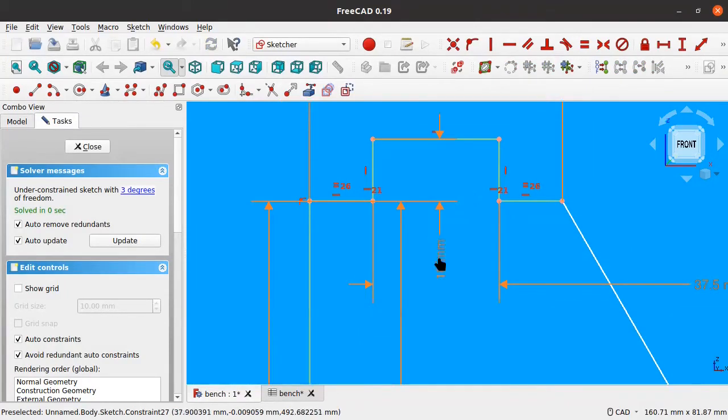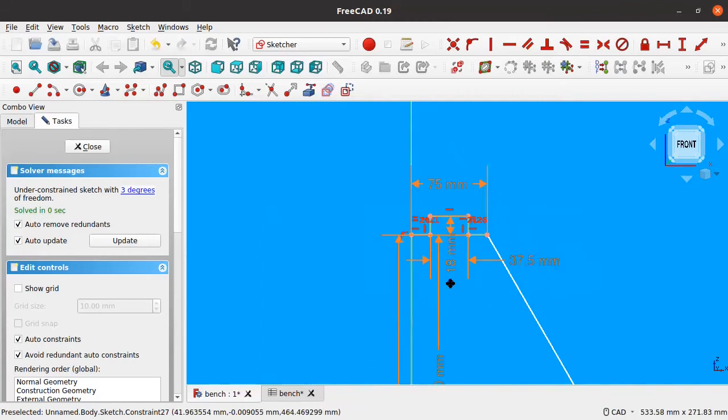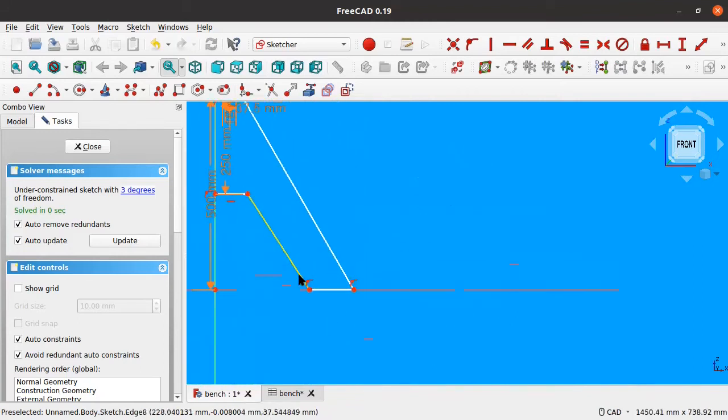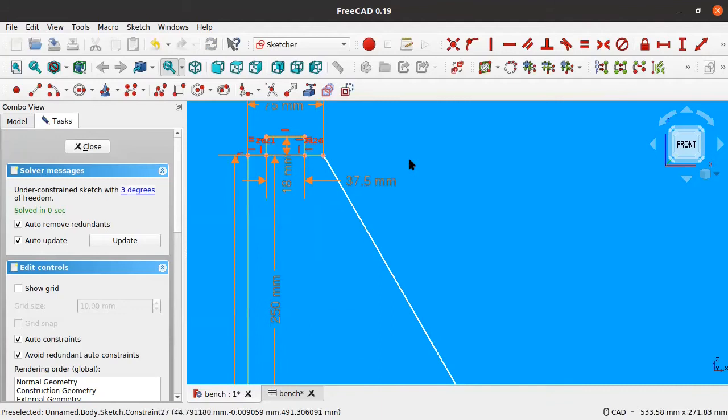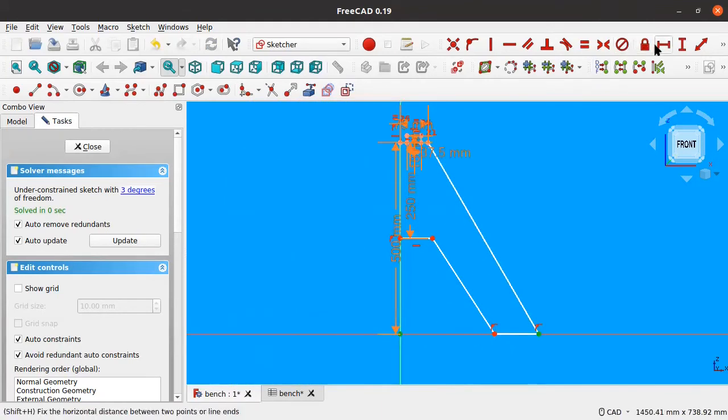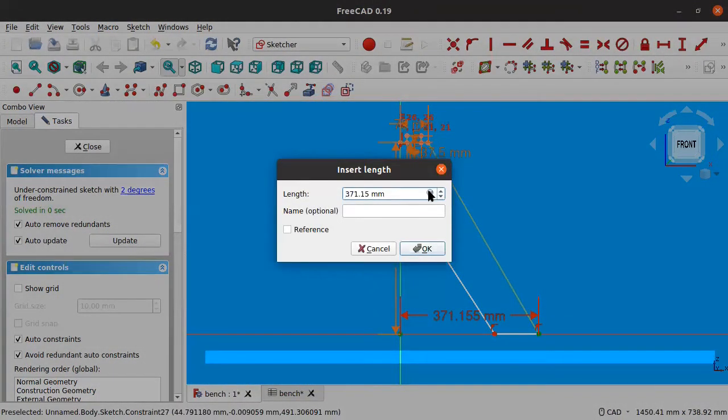Here it's 18 millimeters at the moment. Now, I want this dimension, the footprint of it, so the radius of the footprint, to be equal to the actual diameter of the seat. We can do this by adding a horizontal dimension.